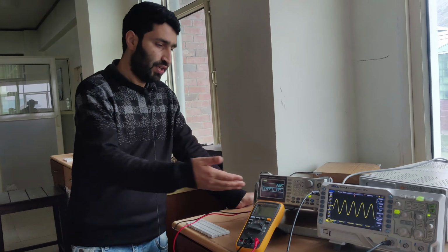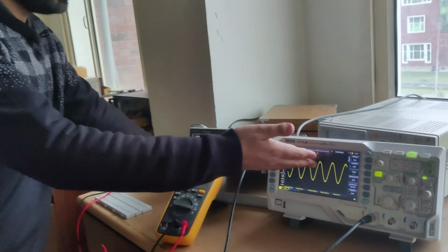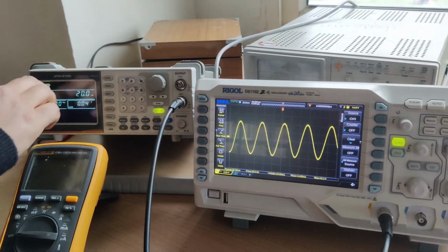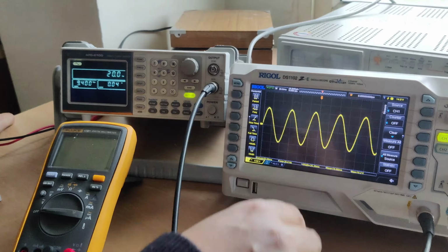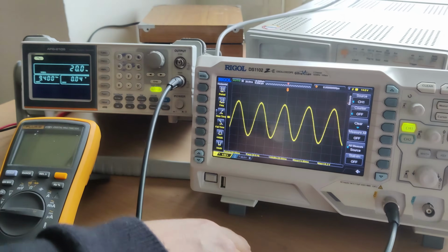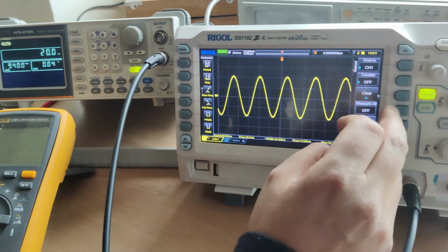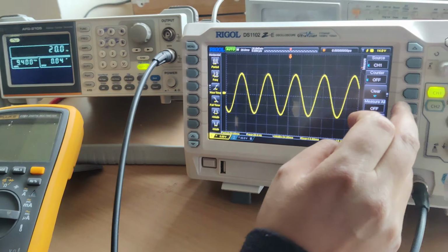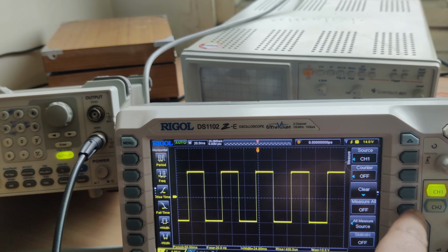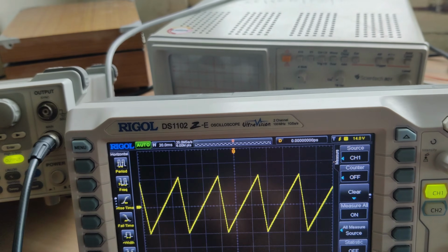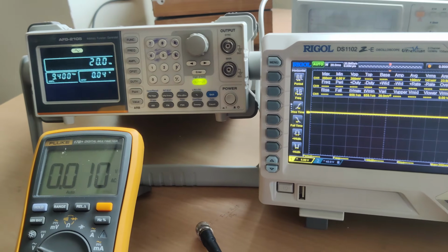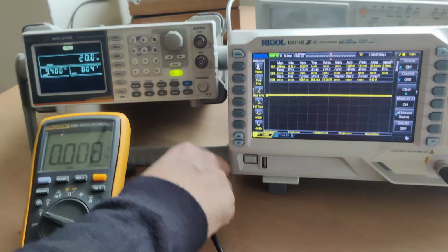As you can see, we have a setup here. Right now you can see the sinusoidal signal on the DSO, whose input I have given from the function generator. You know the RMS value of a sinusoidal signal is very different from the square wave as well as from the sawtooth waveform. When we mathematically calculate the RMS value of a sinusoidal signal, it is Vm divided by root 2. The RMS value of a square wave is Vm and of the sawtooth waveform it is Vm divided by 2. So let us practically see what is the RMS value of these signals.